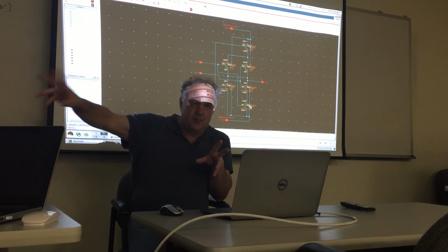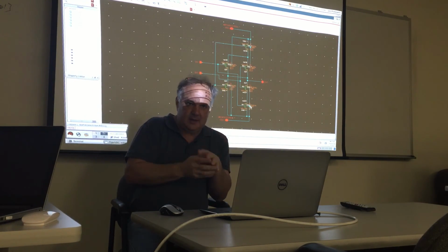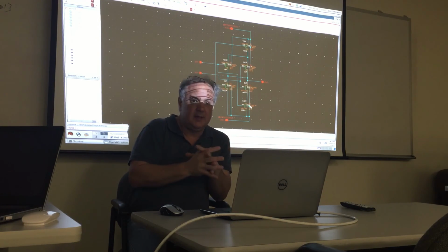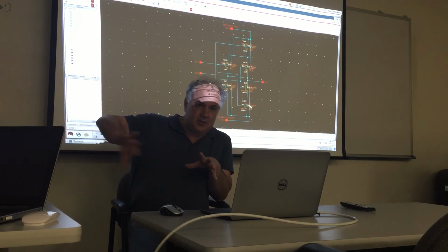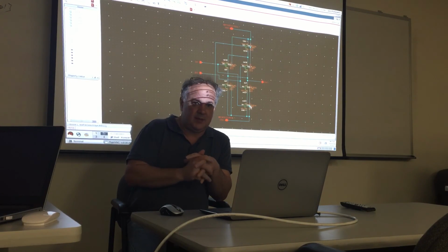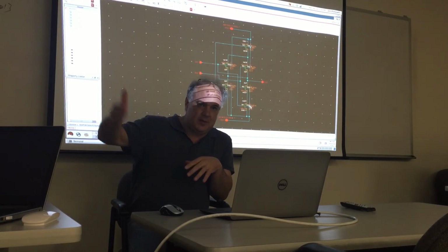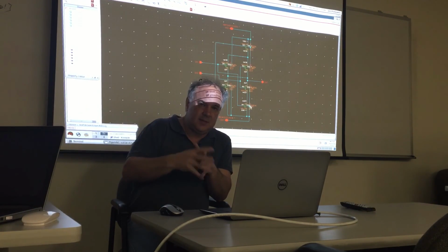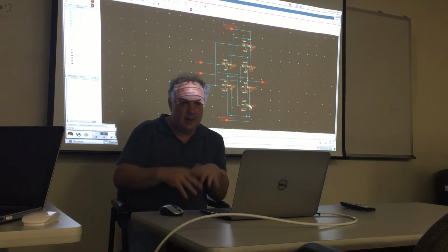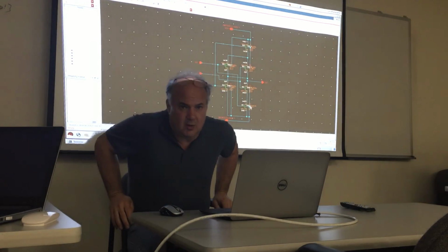Remember, you're not driving an output node, so you just gotta make it reasonably fast internally. So you have some flexibility. It's only the output node that you have to pay attention to, because the tool is gonna depend on having various drive strengths in order to size up or down depending on how much fanout it has. It's gonna do all that automatically.